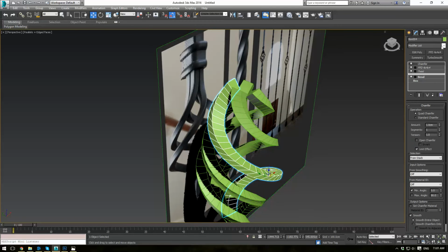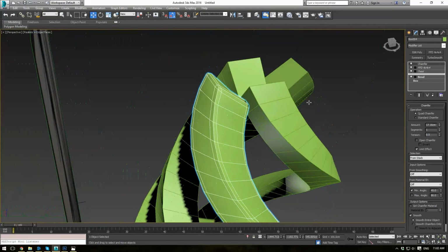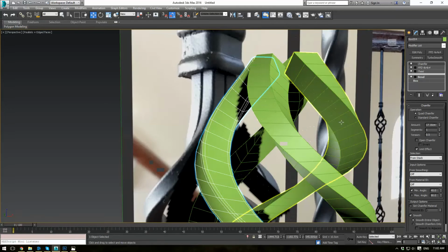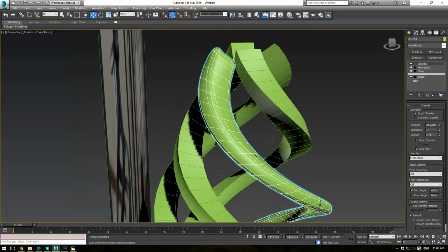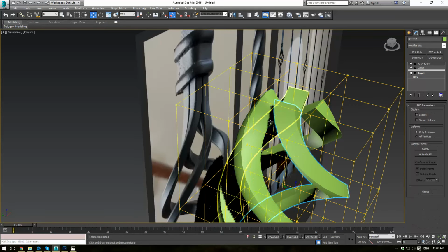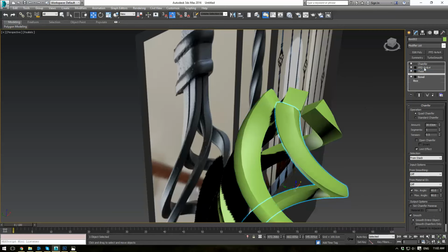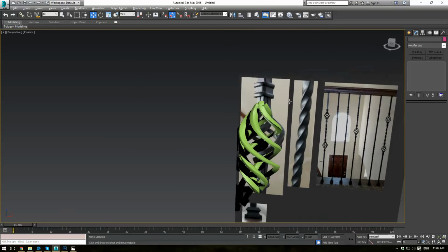And then if you chamfer it, you're going to see all the lines are chamfering. So go ahead and bring your minimum angle up to something like 45. And that'll get you just the ones you want. And go ahead and make sure it's a quad chamfer, bring the tension to about 0.5. That'll give you a nice sort of rounded edge. And maybe we can bring it up just a little bit, maybe 0.75 there. And too much. We'll leave it at 0.5. Since it doesn't seem to be wanting to copy that, go ahead and just drag the chamfer to the other pieces there. Alright, so that's the main basket.